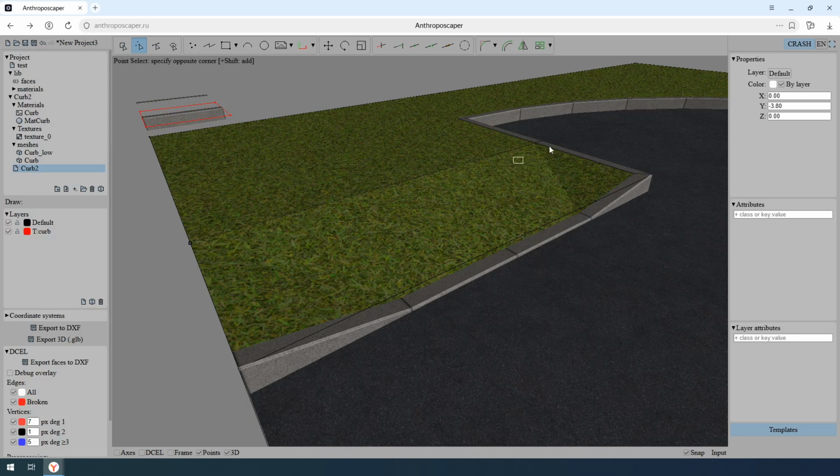I select the points on this edge and give them normal up. A forced vertical normal. Lighting is computed from normals, and now at these vertices the normal points straight up, and the computation smoothly stretches the shading across. I rebuild. The sharp boundary is gone, and in its place a soft gradient transition. The face stayed the same. Only the way it's lit has changed.